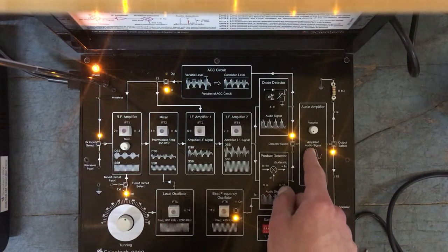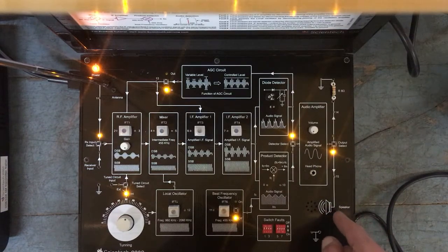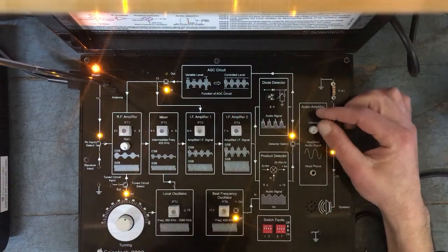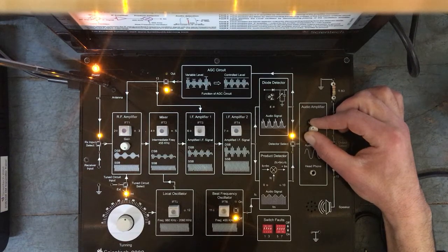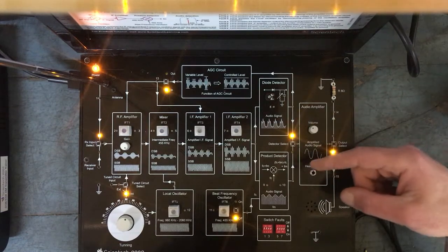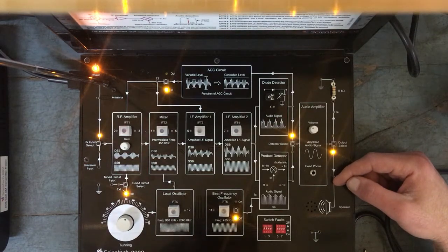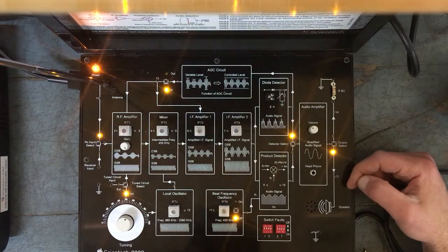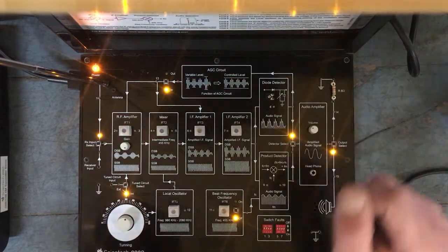This gives a large gain to almost 10 volts, which would be sufficient for a speaker to function. And now let us increase the volume and see what we are receiving in this case. This is the exact signal which we are receiving, which is 3 kilohertz, which we had sent as our message signal. In order to confirm that, we can first do the tuning.